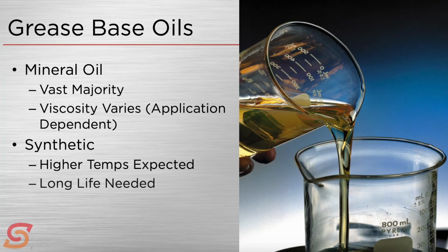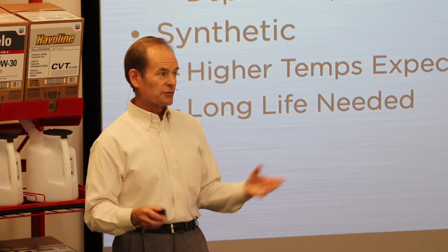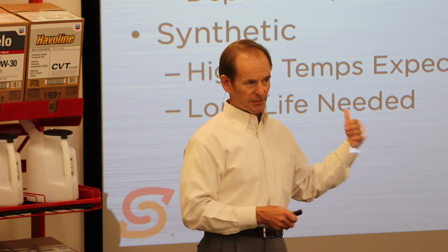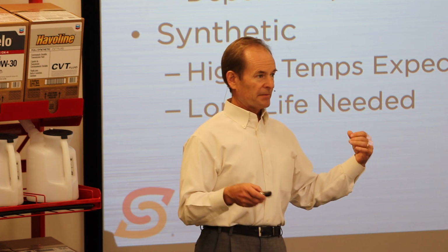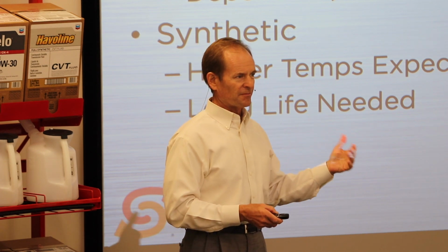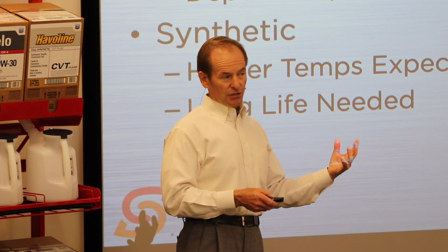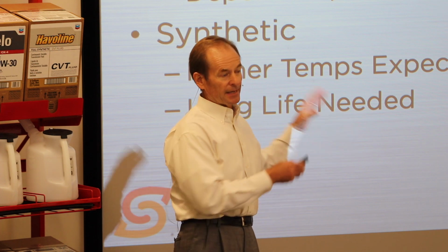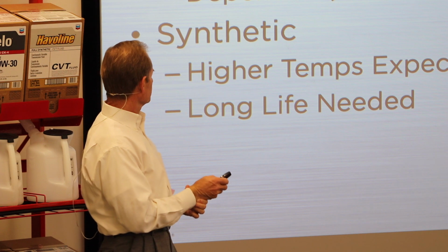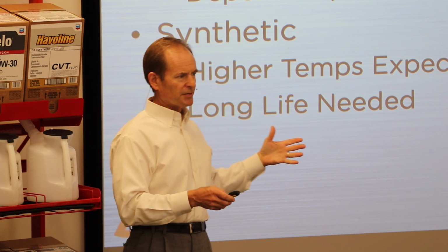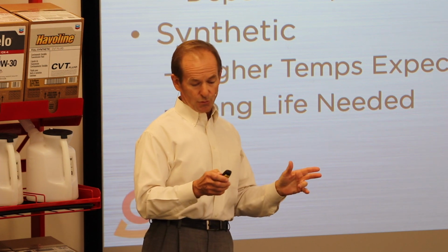And also, where very long life is needed. Okay? In fact, you would think this is a natural for any sealed for life bearing. It ought to be a synthetic, and many of them are. But I'm constantly surprised that many of the sealed for life bearings are using a grease that's not a synthetic. It's just that it lasts a long time, but the duty is not so severe that it's creating a lot of heat. And that fighting the heat stuff is where the synthetic really kind of shines. All right, so that's our base oil. Minerals and synthetics, really mostly minerals. It's the viscosity that's important.